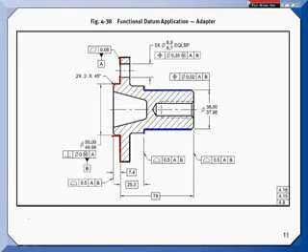In assembly, they couldn't get the screws to go in because there wasn't very much clearance in the clearance holes. So then they measured the pitch cylinder's axis, and there was up to a 13 thousandths difference in some of them, which was enough to cause interference, and they couldn't even start the screw. So there can be a significant difference.